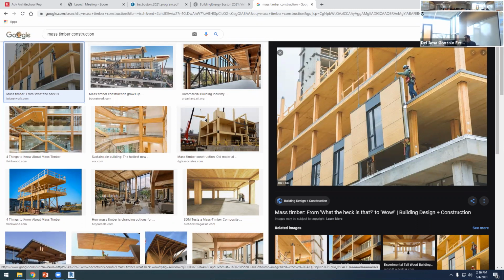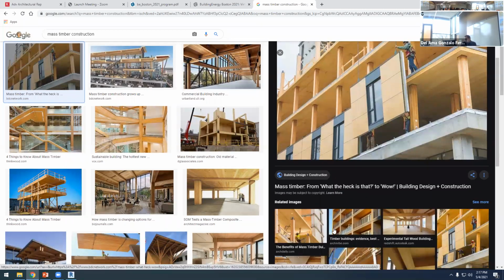So usually we fabricate these panels in a workshop, and then we place the panel with a crane. We place the panels, but as you can see, we have the thermal insulation, the finish, the window, the operable window. So everything is on the same panel, and then we place it on site just by connecting this panel to these elements here. Okay? So this is a more reliable construction, and it's becoming mainstream now.